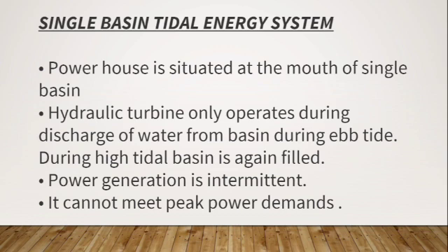Single basin tidal energy system. The powerhouse is situated at the mouth of the single basin. The hydraulic turbine only operates during discharge of water from the basin during ebb tide. During high tide, the basin is again filled. Power generation is intermittent. It cannot meet peak power demands.